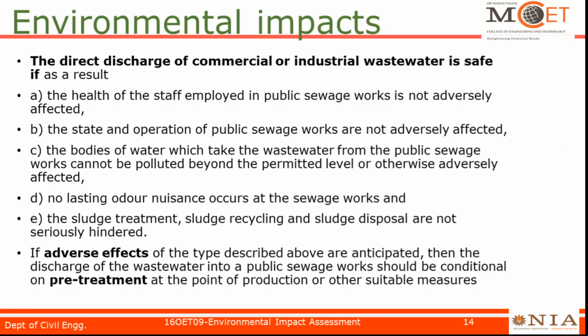The direct discharge of commercial or industrial wastewater is safe if, as a result, the health of the staff employed in public sewage works is not adversely affected. The state and operation of the public sewage works are not adversely affected. The bodies of water which take the wastewater from the public sewage cannot be polluted beyond the permitted level or otherwise adversely affected. No lasting odor nuisance, that is smell, occurring from the sewage works. The sludge treatment, sludge recycling, and sludge disposal are not seriously hindered.